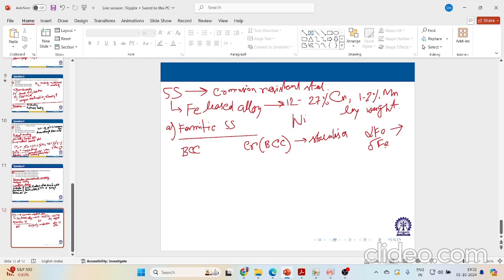So, yeah, if you see this phase diagram for iron chromium, we'll understand what I'm talking about in terms of alpha, delta, and gamma. Let's not go in the direction of the iron chromium phase diagram, that also I need to refer. Anyhow, this alpha ferrite and delta ferrite merge to form the gamma loop. Okay, so that will happen there.